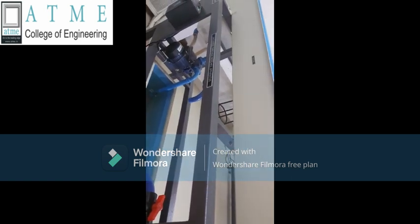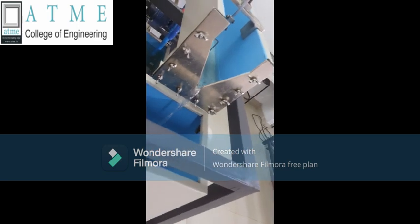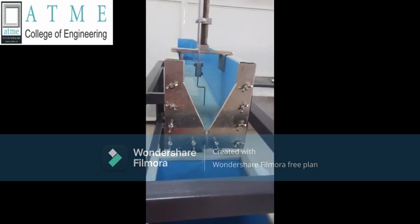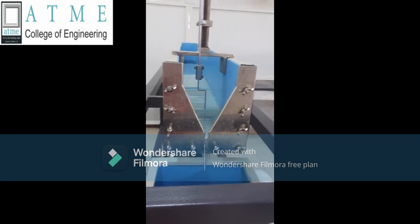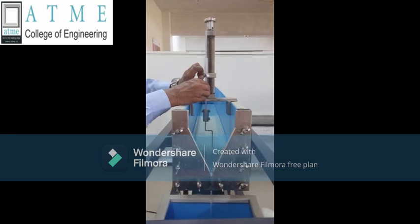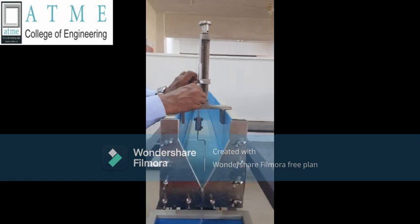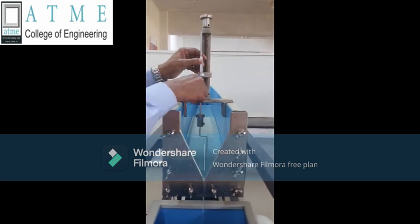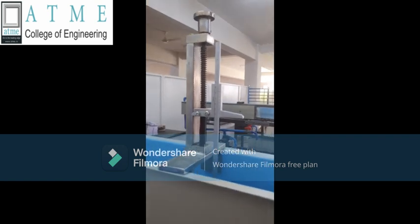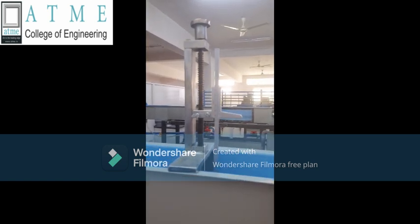Switch on the motor and allow the water to flow over the channel and wait for some time until the water comes up to the crest level. Once the flow becomes steady, adjust the point gauge such that the point gauge tip has to touch the top surface of the water. Note down the height of the water as H. It remains constant for all the conditions.